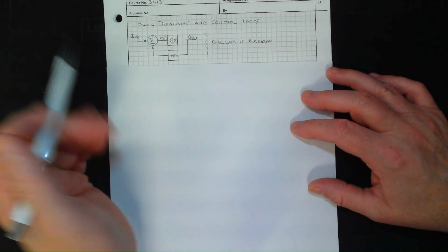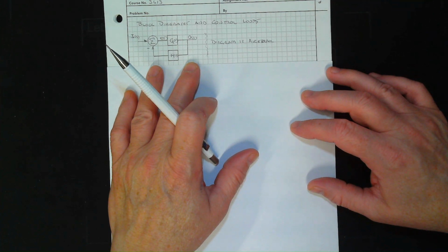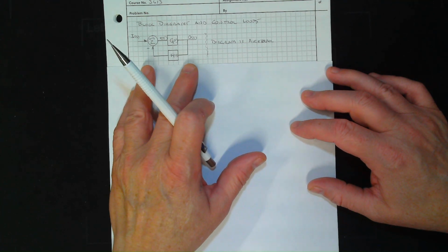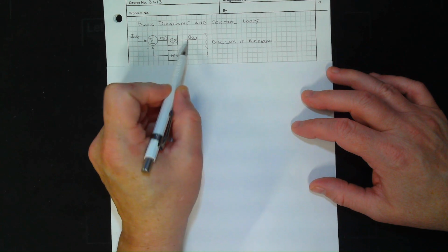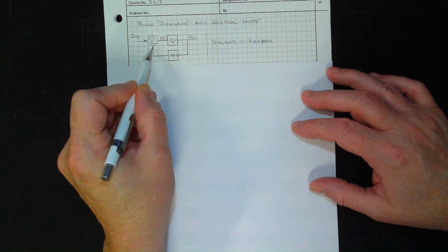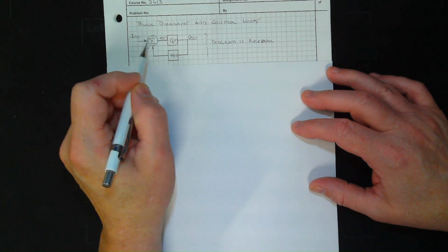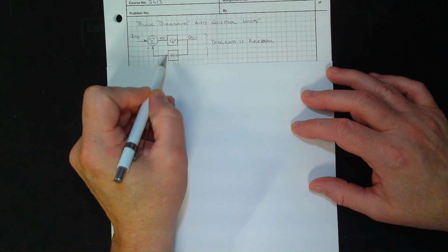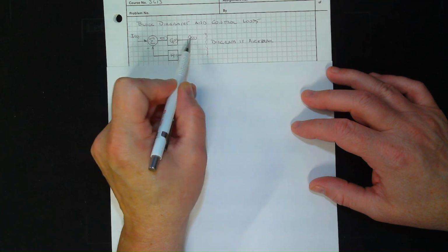All right, block diagrams. So here is a block diagram. You see these are blocks. This is a summer, but this diagram lives in the Laplace domain, and it's totally algebraic. Here's a summer. So we have I of S, and here you have the output. It goes through some filter, H of S, and comes back negative. So I of S minus O times H of S equals E of S. Now if H is functionally 1 here, this will be the error. Then E of S times G of S equals O of S.